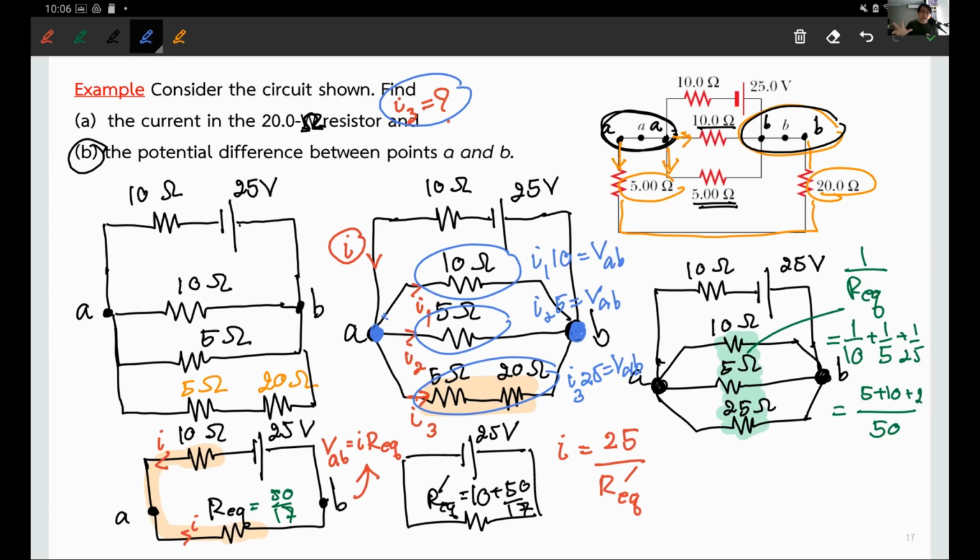However, the understanding here is that every time you're talking about two points, A and B, no matter which type of connections you have, the potential across A and B is still the potential across A and B. If there is a three-way split, the potential across each wire must be V_AB, so you can use this fact to calculate the current flow on each wire.